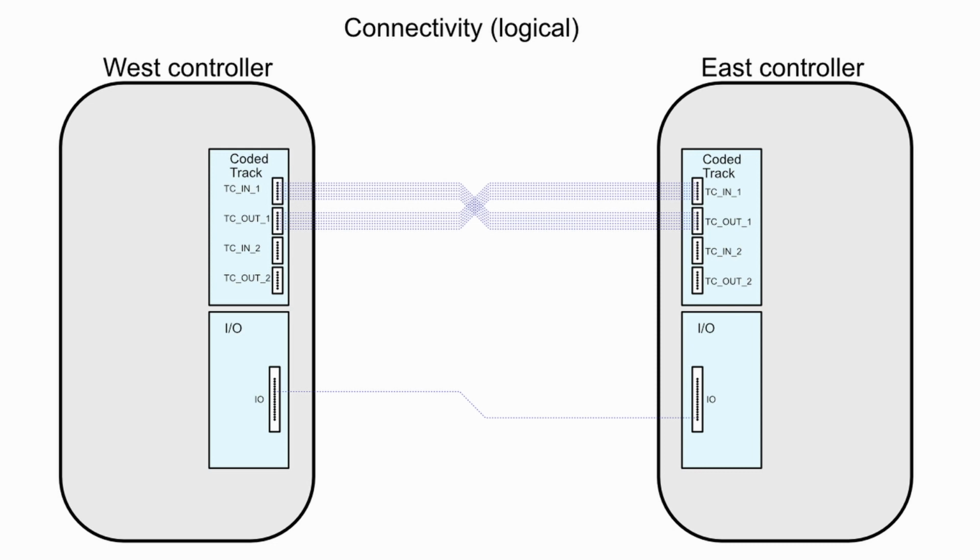of physical connections. In contrast, general I/O cards transmit individual DC signals, which are physically and logically treated in the same way. An I/O card will typically have a set of inputs and a set of outputs, which can be mapped to user-specified tags. Now let's see how to set up these two different types of communication in VitalSim.